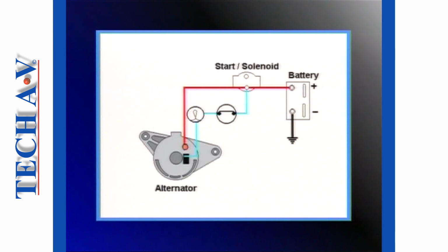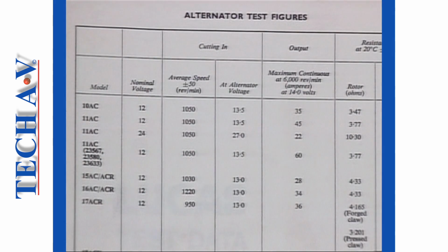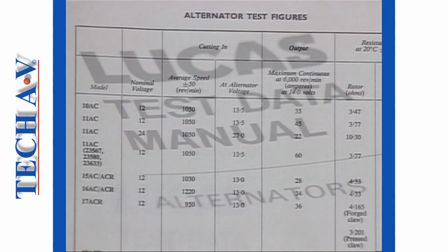As there is now a zero potential difference in the lamp circuit, no current flows and the lamp goes out. We have described the basic principles of a typical AC charge circuit. Differences in design, circuitry, and layout will occur between the various vehicle and component manufacturers. For more detailed instruction on a particular make or system, you will have to consult the manufacturer's service manuals.